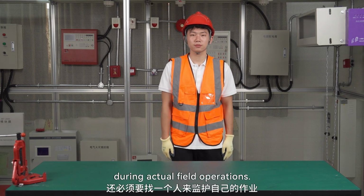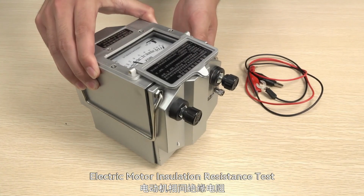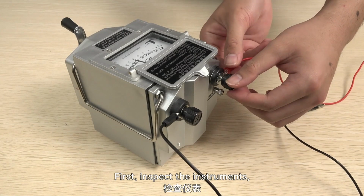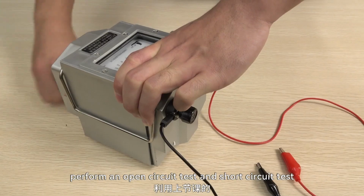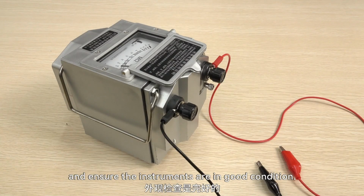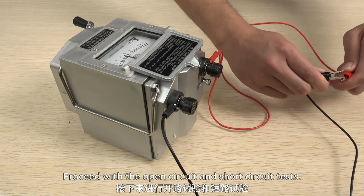Electric motor insulation resistance test, phase-to-phase and phase-to-ground first. Inspect the instruments, perform an open circuit test and short circuit test as covered in the previous lesson, and ensure the instruments are in good condition. Proceed with the open circuit and short circuit tests.